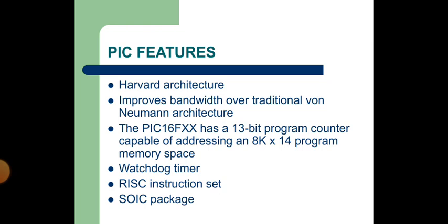Another feature of the PIC is that the PIC16FXXX has a 13-bit program counter capable of addressing an 8K by 14 program memory space, which is efficient. It has a watchdog timer. It has a RISC instruction set and an SOIC package. Well, let me break down these two for you to understand them, because you're going to need these terms later on in this lecture.